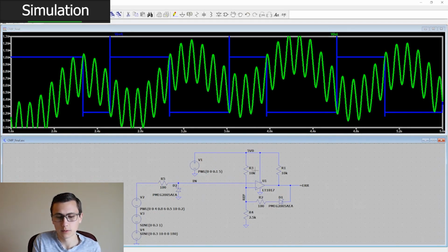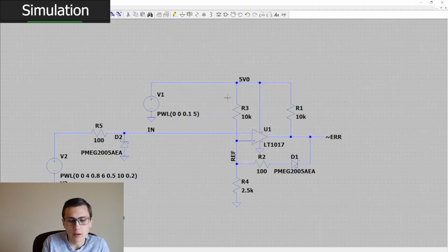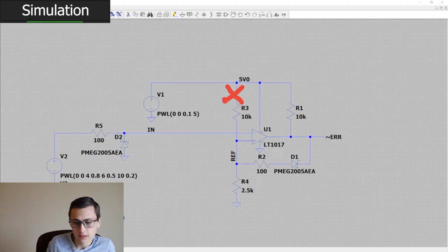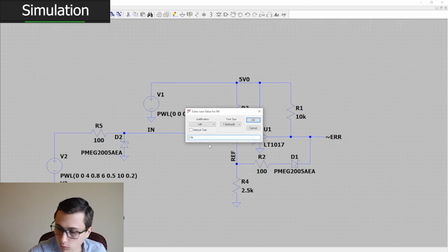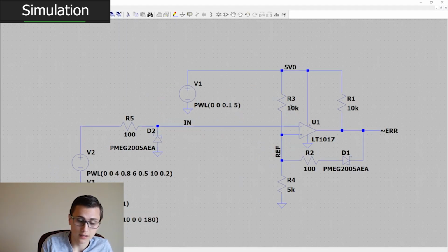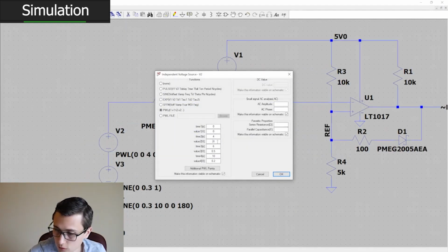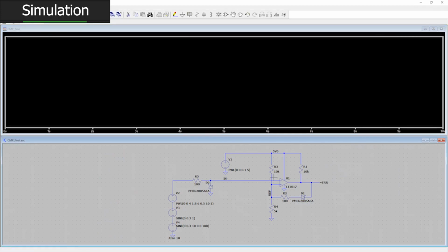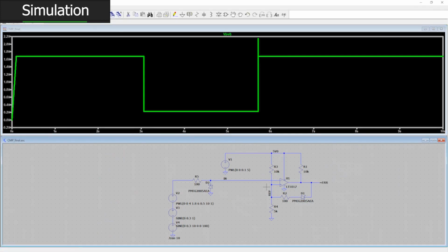Let's just for a moment brainstorm how we might be able to make this a little better. What we really want to do, the pinnacle of what we would like to do, is basically cut this trace whenever the error trips. That would be perfect. There's a couple ways that we could do that, but that seems a little out of scope of what we're trying to do today. So perhaps what would be more relevant is if we pretend that our threshold was actually a little higher. I'm not going to recalculate the voltage divider. I'm just going to move our threshold around. Let's run that and see how we do. So our reference is now right around 1.7 volts.